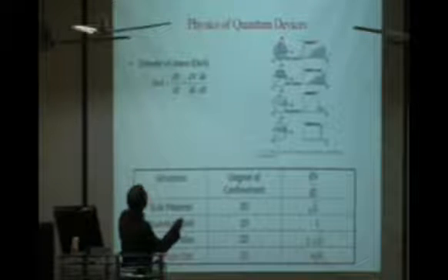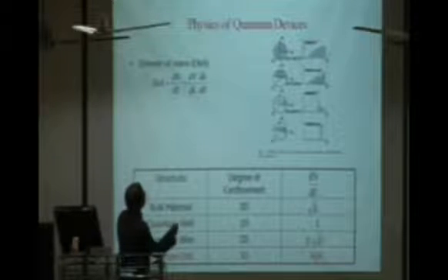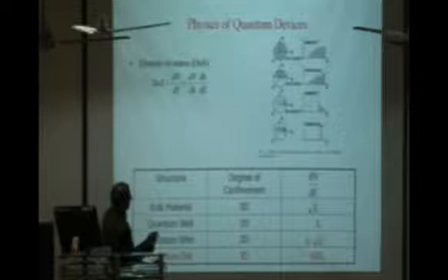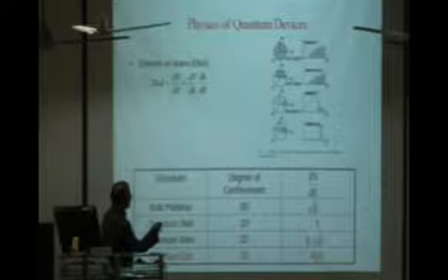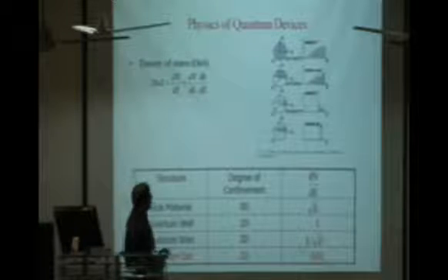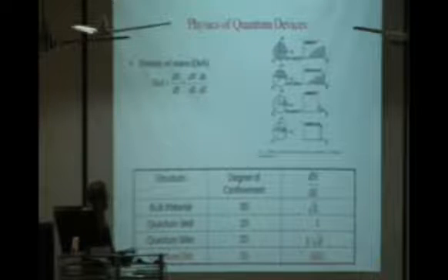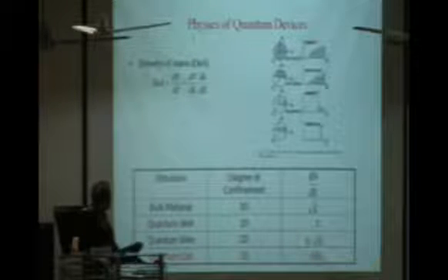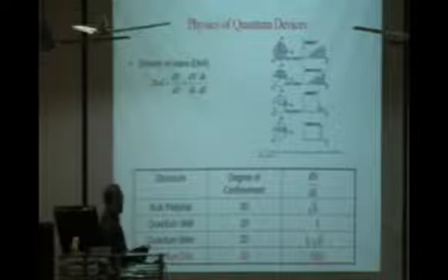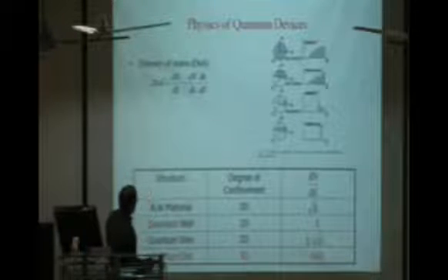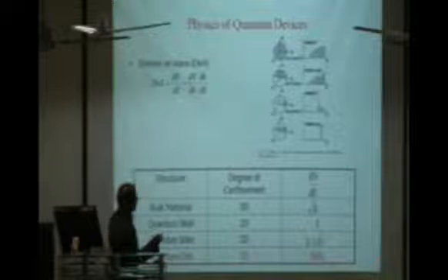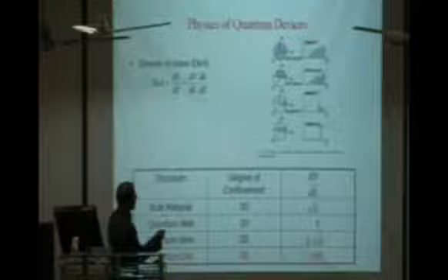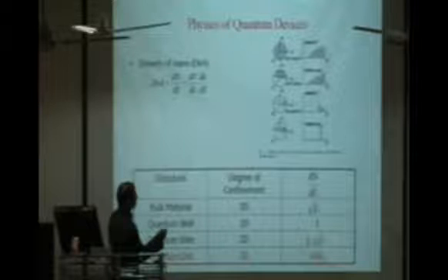This is the density of states on the y-axis and this is the energy on the x-axis. So of course it's parabolic in nature. As soon as you reduce the dimension and make it a 2-dimensional quantum well, it behaves with staircase characteristics. The exact dependence has been plotted here. In the case of bulk material, it is proportional to E to the power half, and in the case of a quantum well, it is independent of energy. It only goes to the next energy level, but for the same quantum number it is independent of energy because this remains the same.